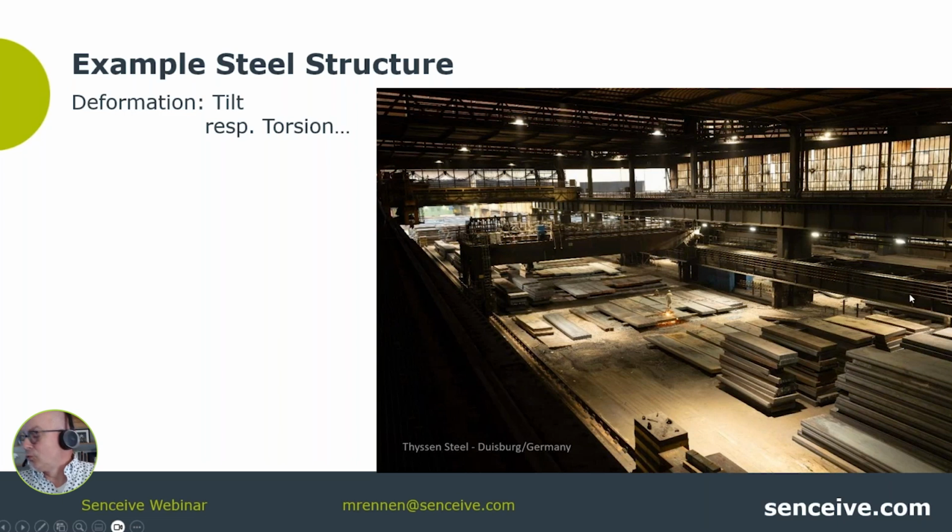And these huge beams here, they have been experiencing damages in the past. Now, this is mainly caused by load and then the torsion of the crane or the beam itself. And when you then see cracks here, they can be repaired by patching, welding some patch on top of it, but this can only be done a limited number of times.